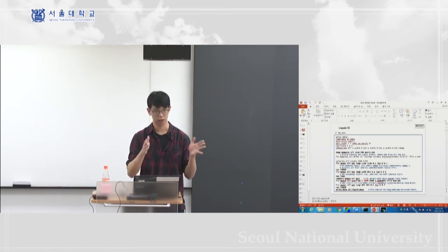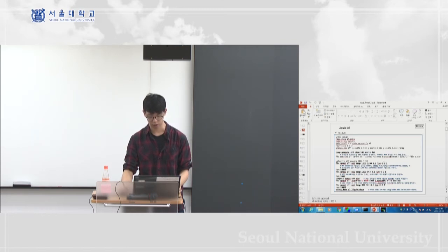We're just gonna let it vibrate by itself. And the next number is the final pressure, which is also 0. And the last number is the damping term for the pressure. And usually we set the damping term for the pressure to 1000 times the time step, so it's gonna be 1 picosecond.